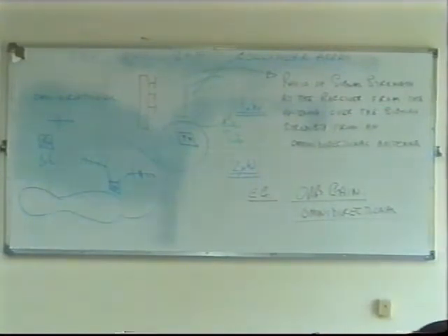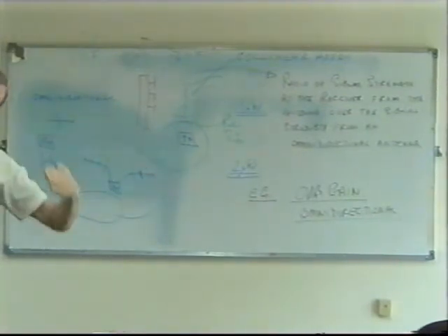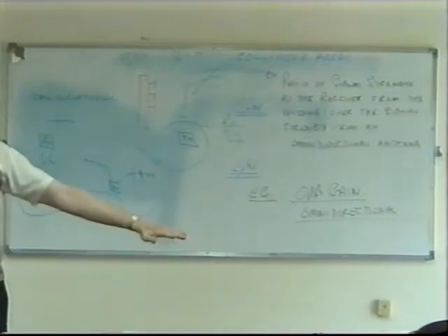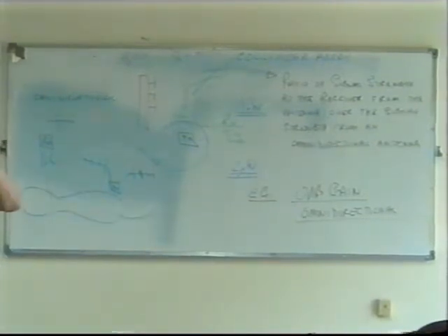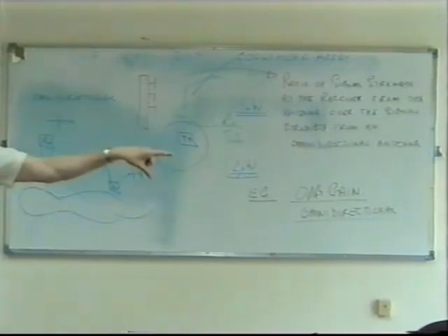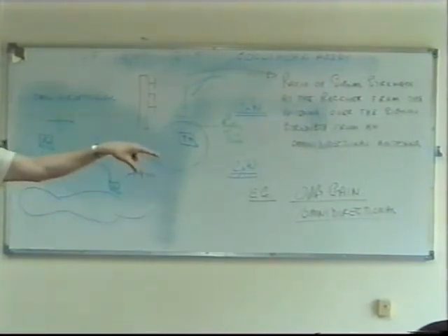Obviously, the higher the power, the better the chance, as long as the idea is to keep your signal above the noise level. Now, if you're going to try and communicate with a mobile station through buildings, then as your signal passes through those buildings, it's going to be reduced quite considerably in power, particularly at UHF. So if you still want to communicate, you want to make sure you've got sufficient power.